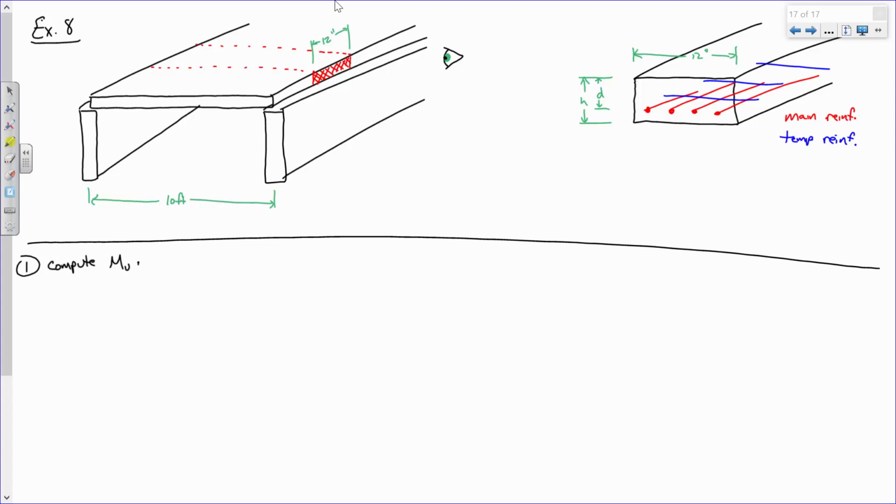I've got a simply supported beam in this case. It's 10 foot wide, right? And so I'm going to have a distributed load on there that's going to be its self-weight, and so it'll be like WL squared over 8 to get the moments. But how do I compute that distributed load? We've done it a few times already. You've got to figure out the area, and then multiply it by the... You're on the right track. Load. Well, no. Ultimately we're going to compute the self-weight, which is gamma times BH. Does everybody remember that?